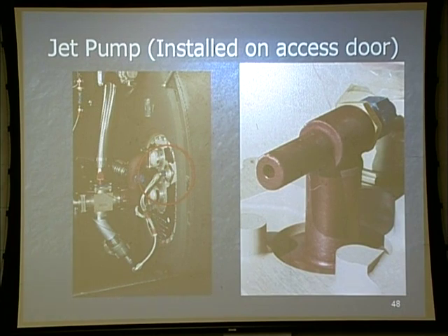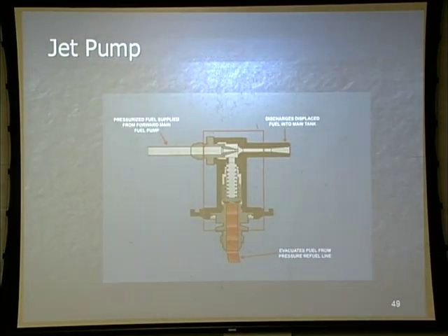Now what I'm going to ask you to do is go to page 16, which you have a picture just like this. So everybody's on the same sheet of music. This different color of red right here is signifying the fuel that is in that pressure refueling line. Everybody understand that? Now, in the top left, this is going to be pressurized fuel via that forward pump in each one of the main tanks. Good?